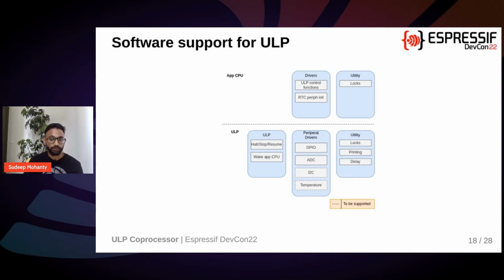Also, there are certain utilities that are shared between the main core and the ULP core, such as a locking mechanism for synchronization. And there are other utilities which help the ULP core perform its activities, and all of these are part of the ULP driver that comes with ESP-IDF.